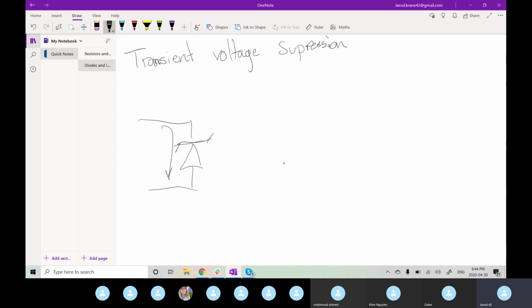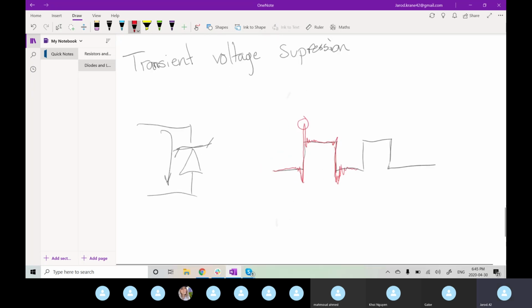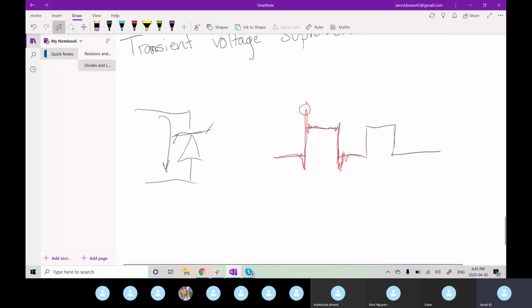So this can be seen in square waves, sine waves, or ESD. As we discussed last time, square waves aren't perfect. There is some ring to them, so they'll have some undershoot, and then they'll come up and have some overshoot, and then they'll do this a bunch. So these peaks are capable of being several magnitudes above what your expected voltages are supposed to be.